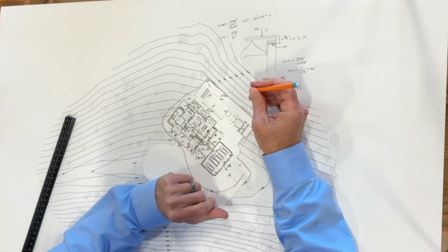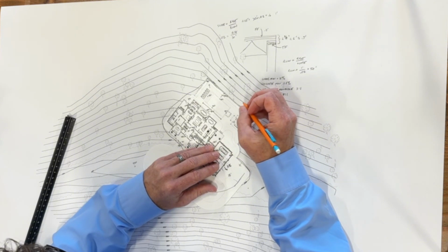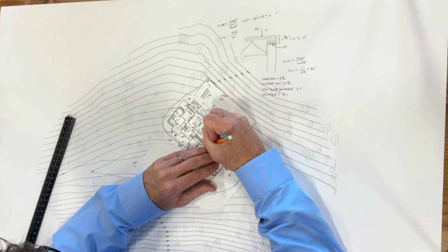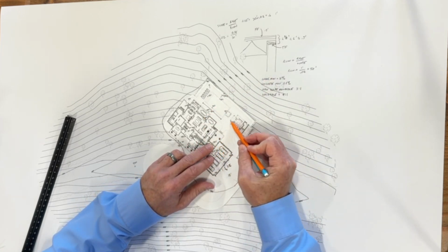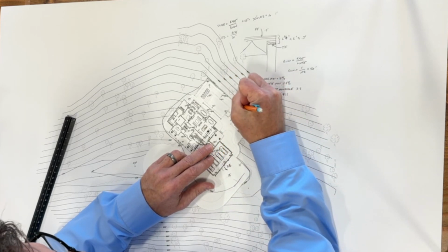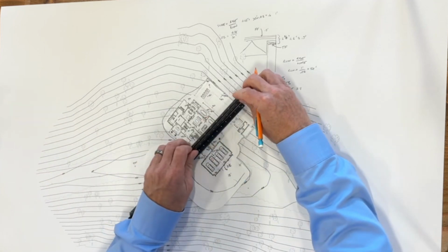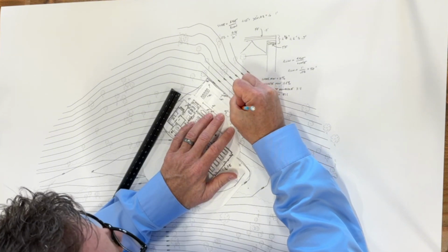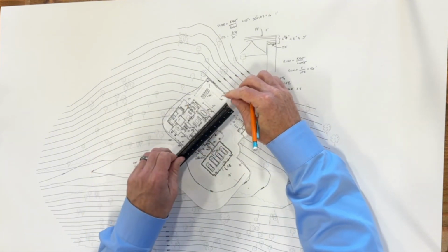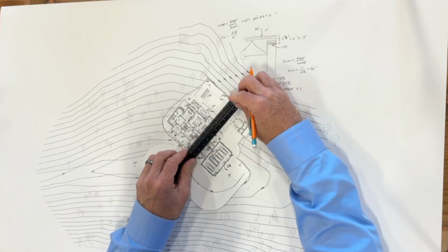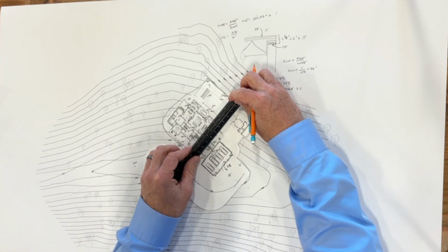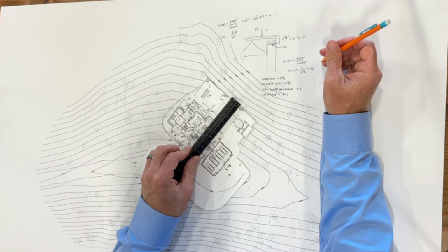Now let's figure out here. Now again, we got to slope a minimum of 2%. And we know that this distance, from this door, a drop of water that lands there is going to want to go all the way across, okay? And that's a 941.5. Let's just see what that slope would be if we made this a 940.5, let's double check that that's going to work. So that's a 1 foot drop, and that is in 70 feet. So what's that slope? So do 1 divided by 70. Just barely less than 2.